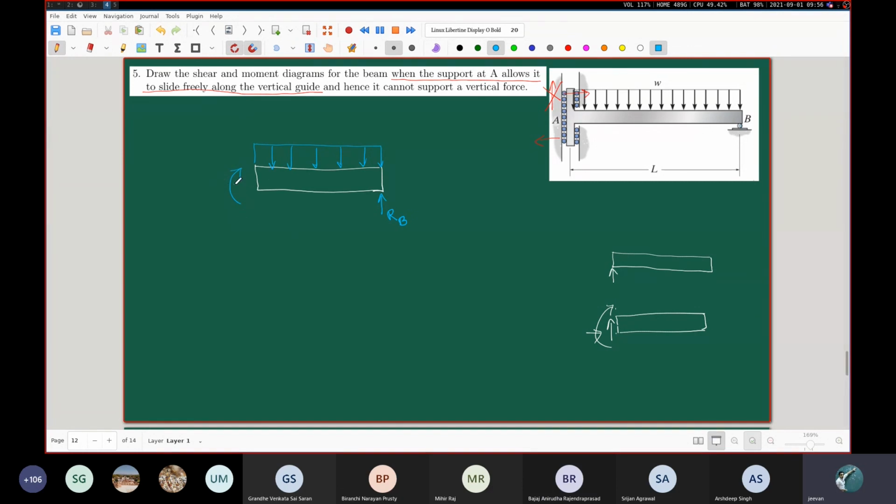You can draw a horizontal force, it doesn't matter. Because sigma Fx equals 0, whatever the distribution of horizontal forces from these rollers, they will internally balance each other out. So that's not a big deal. But suppose I just stop the free body diagram at this point.